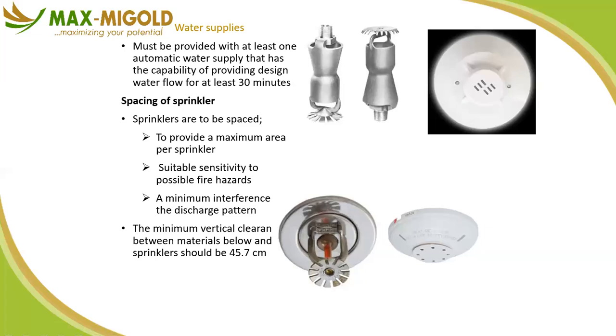But of interest, if you zoom in on these pictures, the lower sprinkler head has something that looks like red glass. That is the sprinkler head's breakable glass. When the heat is high, say 60 degrees C or 70 degrees C, depending on the sprinkler head you bought, this glass will break.